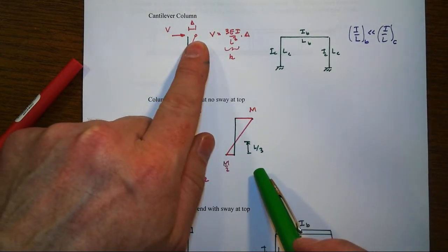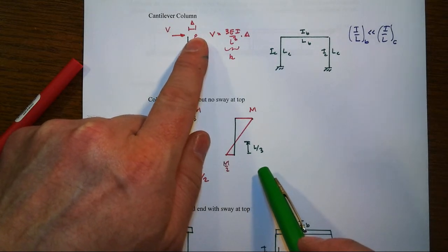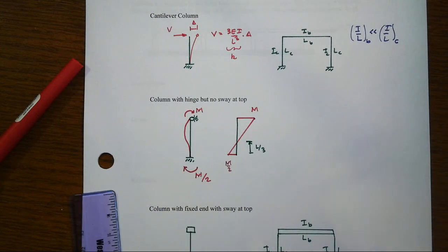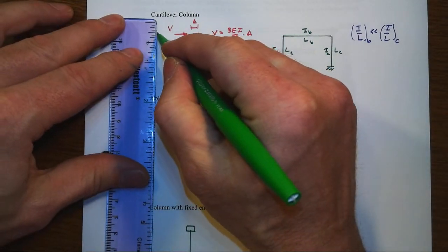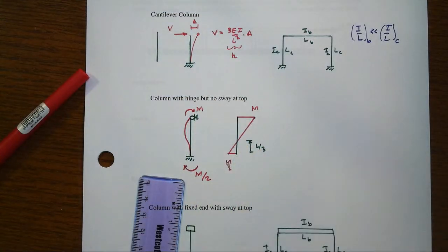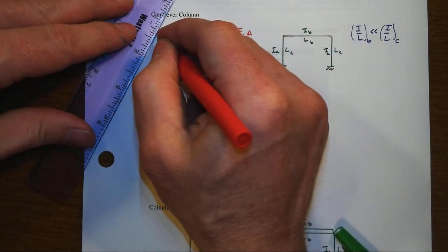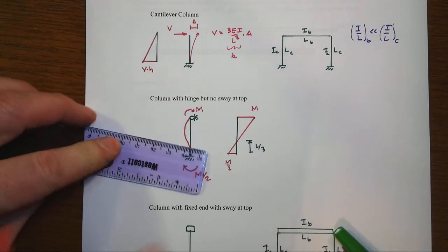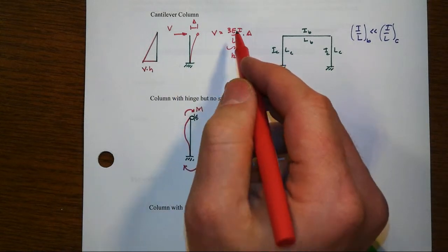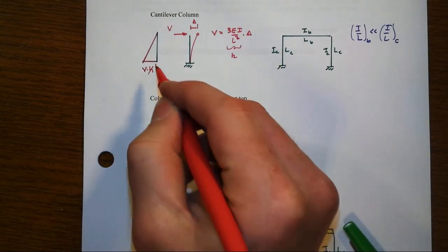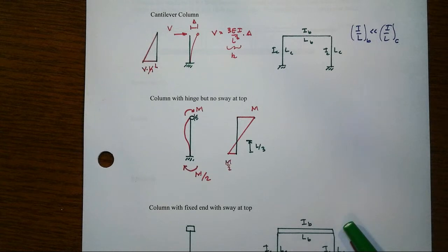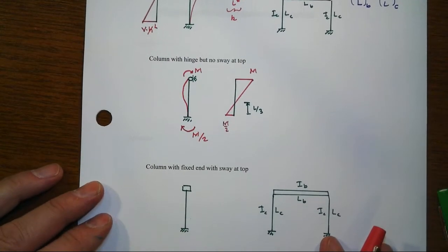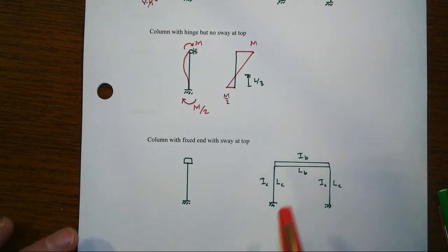Right, so notice the inflection point on the top one is right there at the top. That's where the moment is going to be 0. And there again, if we would like, we could draw the moment diagram that goes with that, and it's just going to linearly increase over the height of the column and would just be equal to V times H, or L. I guess I've got it written over here, so make that V times L of the column. Right, so that's two extreme cases.